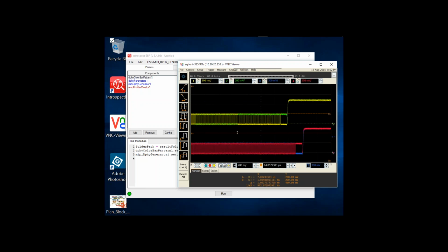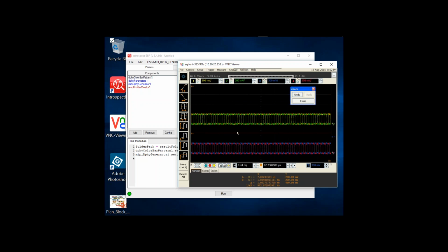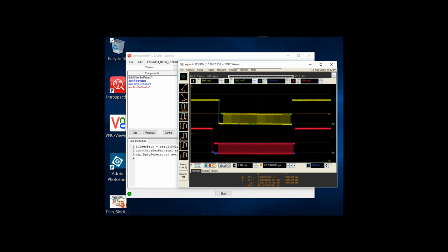Similarly, if we go to other sections of the pattern, towards the center of the pattern in particular here, this is really a high frequency pattern. So it's a 1010 pattern. So the CTS colorbar pattern is really a mixed frequency pattern that has properties that make it useful for isolating and stressing different aspects of the receiver when it comes to electrical testing.